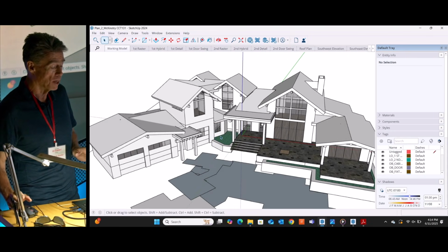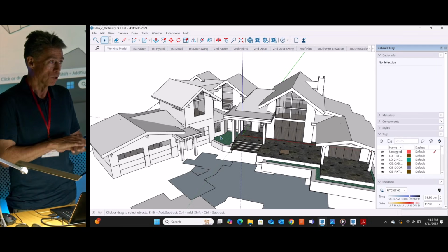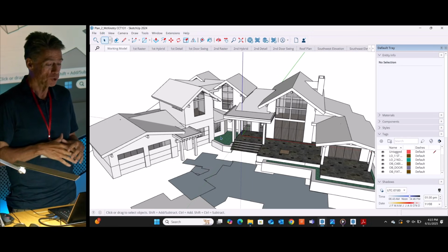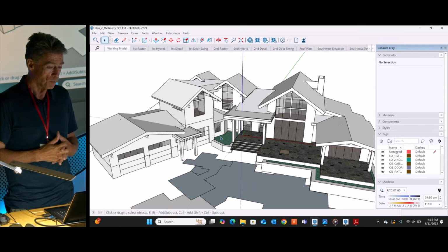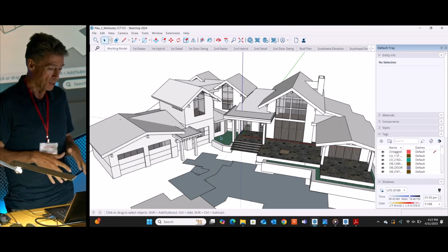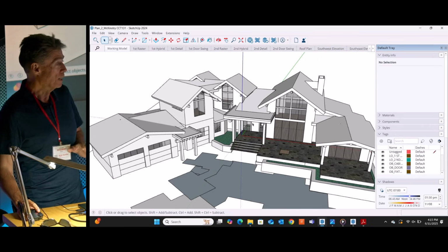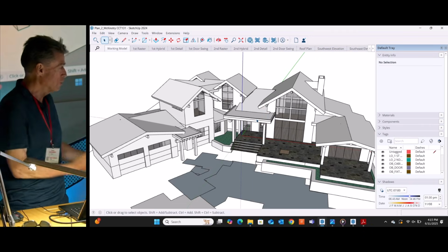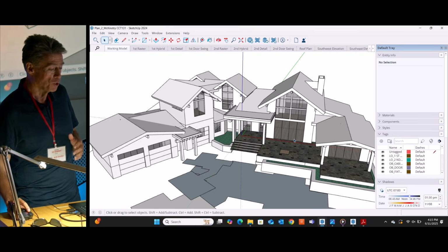The client really wanted to have it not look like the classic mountain modern homes that we see in this development, where it's all long shed, 1 in 12, 2 in 12 pitches, but something that had some traditional roof forms. In this case, I think it's a 9 in 12 pitch we have on the gables, and then some of the other gables are 3 in 12, and then there's a couple of flat roof areas that we use to really mitigate the snow. For instance, at the entryway, this roof is not going to dump snow onto you as you're walking up the front steps, as well as any areas where we do have that potential.